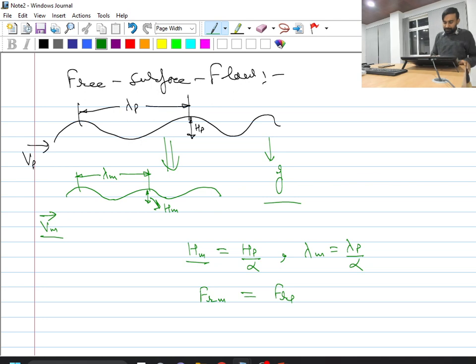What is the definition of Froude number? V square by G L. So Vm square by G times Lm equal to Vp square by G times Lp. G will be cancelling out.